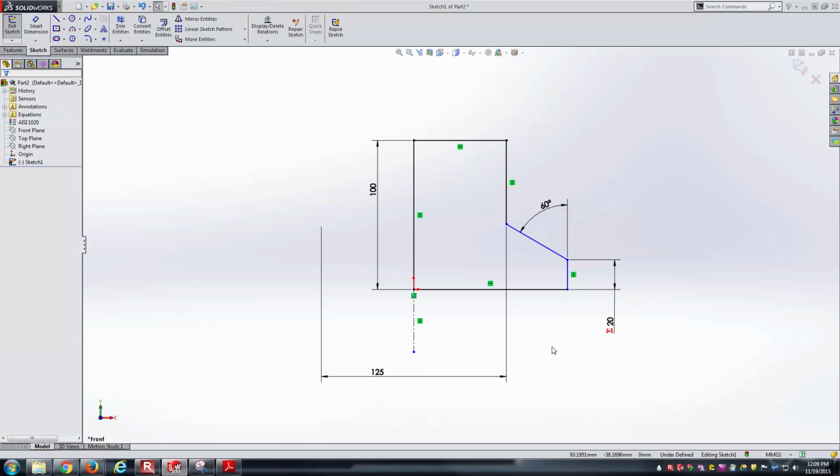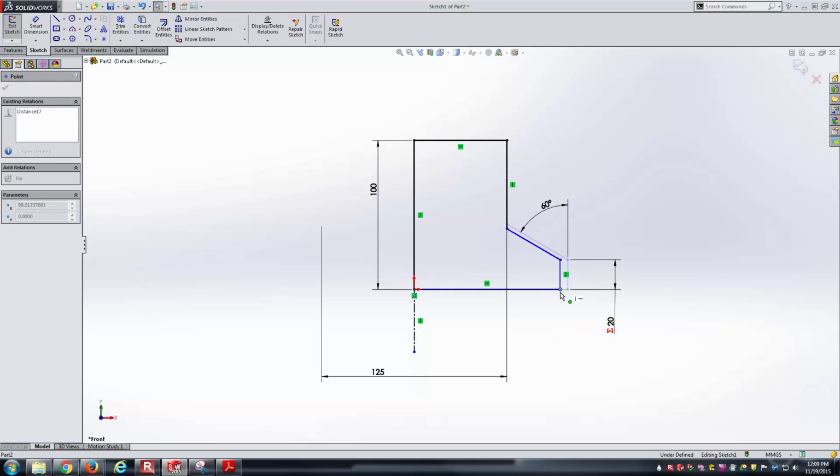And so you can see the notation it gives you inside of SolidWorks. That little sigma in red means that, hey, this thing either has a global variable in it or some sort of mathematical expression. So it could be tied to other dimensioned variables or other items there. But it's just giving you some notes, hey, this is not a hard value. It's got some special things going on.